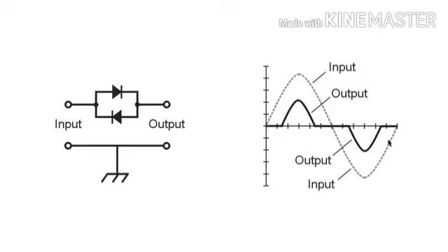Same input as we had before, but a considerably different waveform. Notice that there's no output whatsoever until the input voltage reaches 5 or 6 tenths of a volt positive or negative instantaneous voltage. Once it gets above that, then the difference between the forward breakover voltage and the input voltage is what you get at the output.